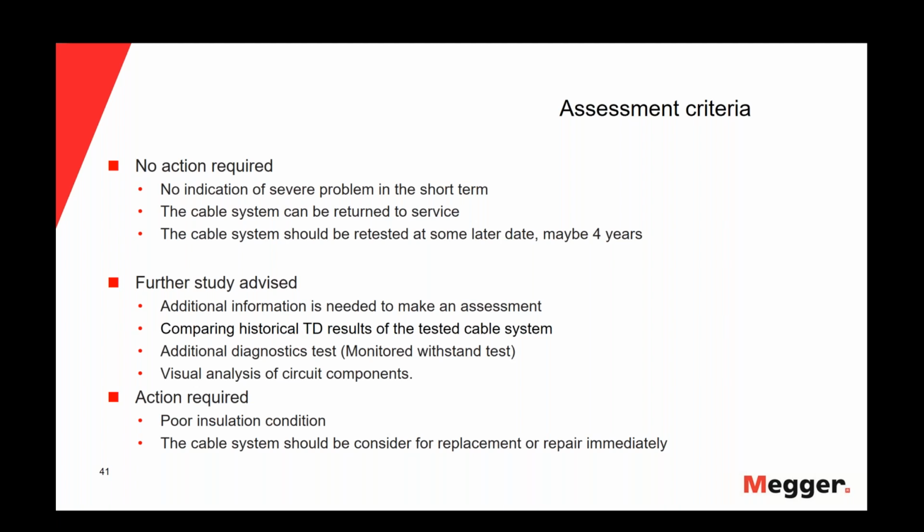It's very important to keep in mind that if we are doing a tan delta test for the first time, we will not be able to make a decision regarding that cable. For instance, if we do a tan delta test and the assessment criteria I get is action required, that doesn't mean that I need to change my cable immediately.